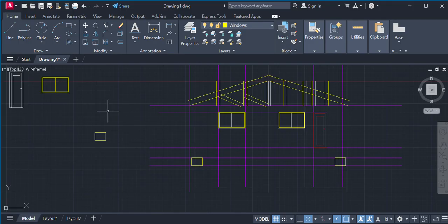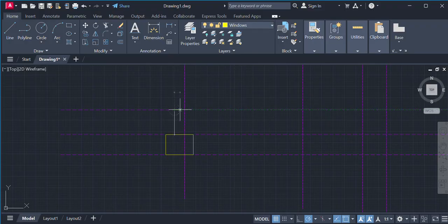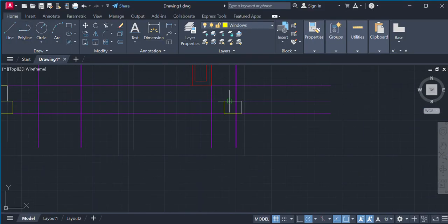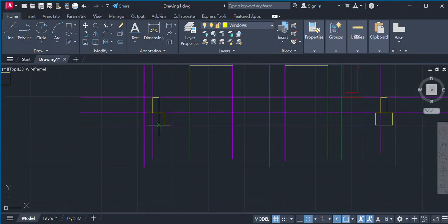So what you can do is to create polylines so that you can have enclosed boundaries. Because remember, at the end, we're gonna need to hatch this whole place out. Then we can create a spline that will essentially show our earthworks.